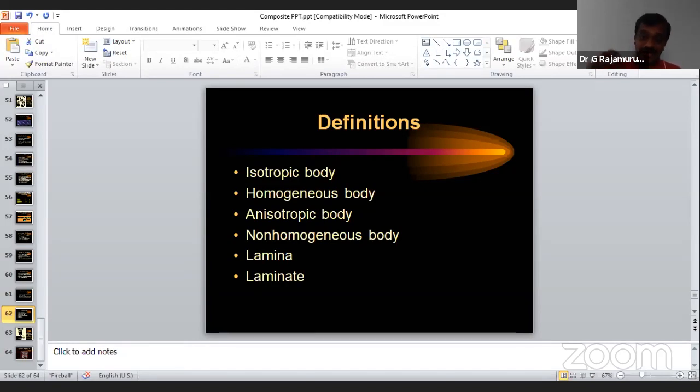Again, there is the problem of the particle settling. If the particle has more density, some of it will settle down at the bottom. If the density of the particle is lower, it will float up on top of the molten metal. You have to overcome that property, and the stirrer speed also plays a major role in distributing the particles evenly in the matrix. Still, some trial and error is going on for optimizing this stirrer speed.